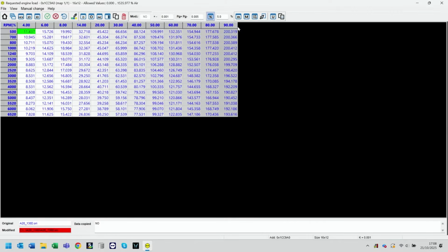Now this is actually torque. On a number of the ECUs, everything from your late 90s through to your mid and late 2000s, even into the early 2010s, it was measured torque as a percentage. So we didn't really have Newton meters coming into the control strategies at this point. It was all based on a percentage of a calculated amount of torque.